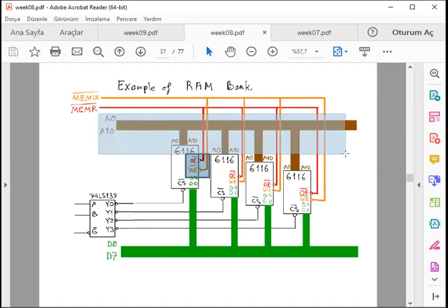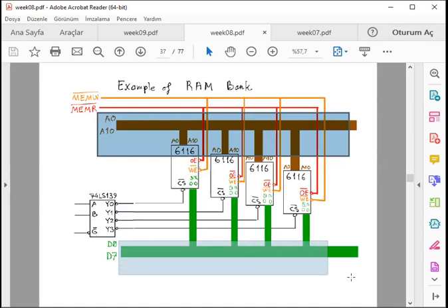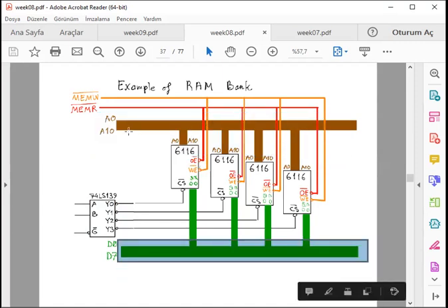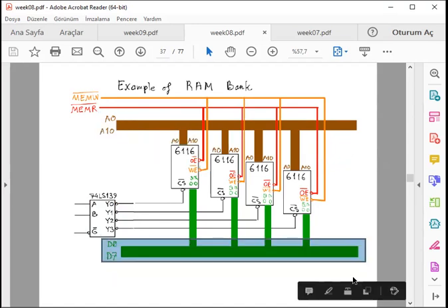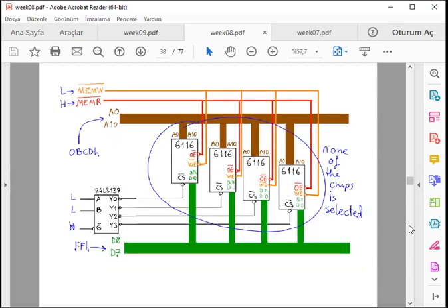The address pins and data pins are as normal, only the numbers are different. We have 11 address pins for this RAM block due to its lower capacity than the 2764 ROM, but the data bus width is the same. It's a byte. Again, examples.